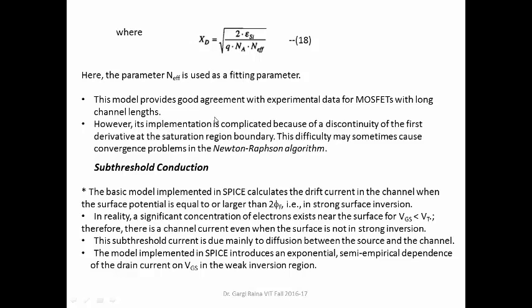But to implement this is a bit complicated, because one has a discontinuity in the first derivative at the saturation region boundary. This difficulty sometimes leads to convergence problems when you are taking the derivatives in the Newton-Raphson algorithm.